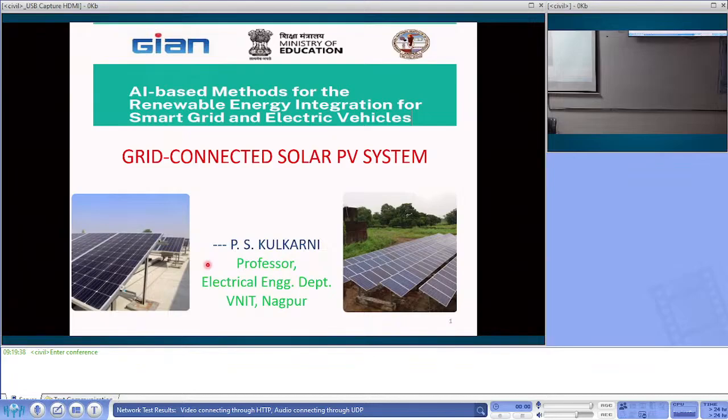I attended one course at the Electrical Engineering Department, IIT Bombay. Long back they had a 2 kilowatt rooftop PV plant on the terrace of the department. After several years when the course was organized, they said that now the output is only 1200 watt. Now the factor which is very important, that brings out the degradation. So the degradation factor is very important when you carry out analysis.